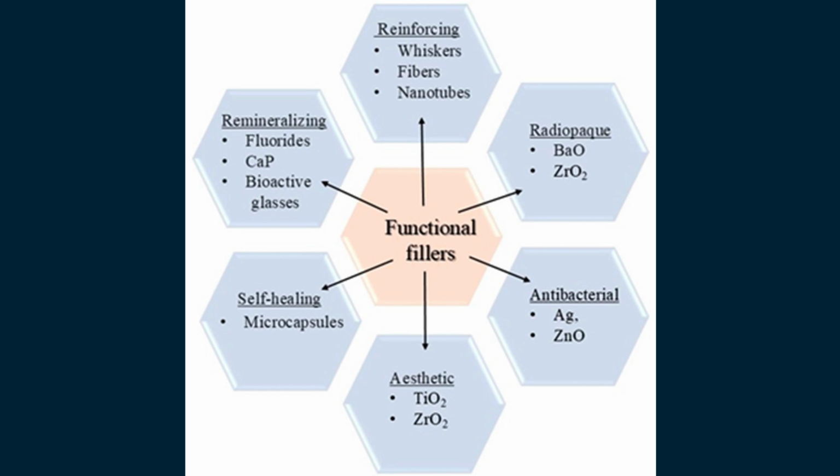Careful control of filler size, surface chemistry, dispersion stability, and loading level is essential to maintain optimal viscosity, infiltration capability, and curing efficiency. Continued research into bioactive and nanostructured fillers is expected to further improve the performance and therapeutic potential of modern dental adhesive systems.